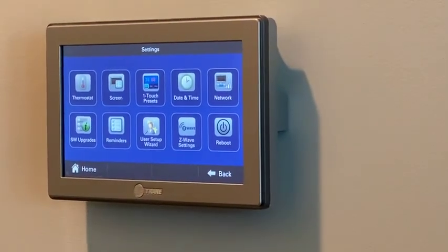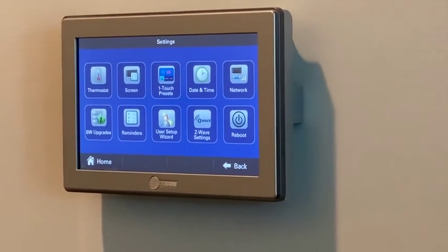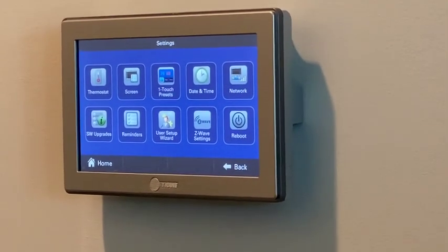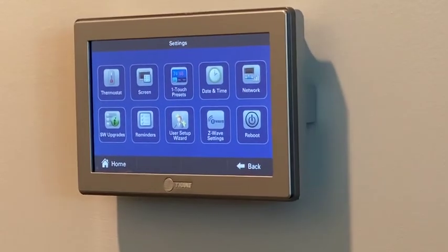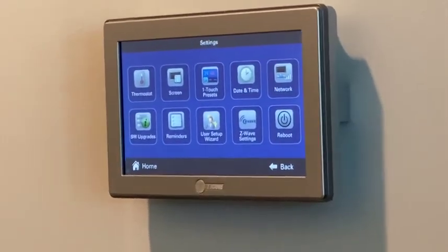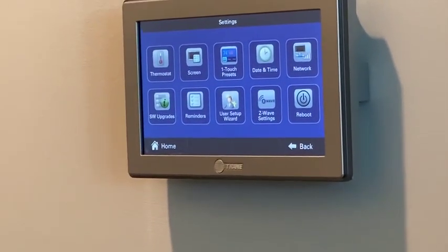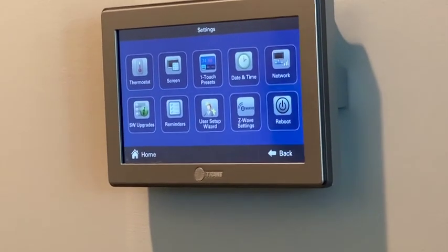Interesting, I didn't know. But in the winter, when it's really cold, and you put it back up, just put it up about 2 degrees, and then wait till it almost hits that mark. Otherwise you'll see it go all auxiliary heat or emergency heat, and that's the heat strips. That's why it's cost-effective. But if you have gas heat, you can do whatever you want, right? Correct. If you have gas, it doesn't matter.